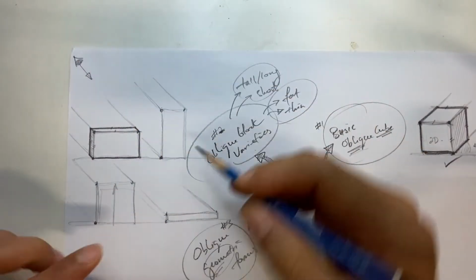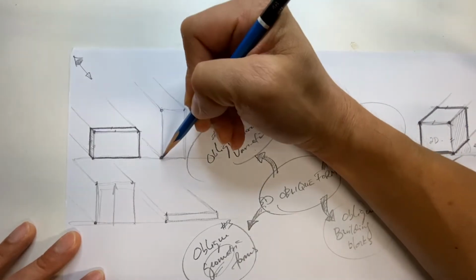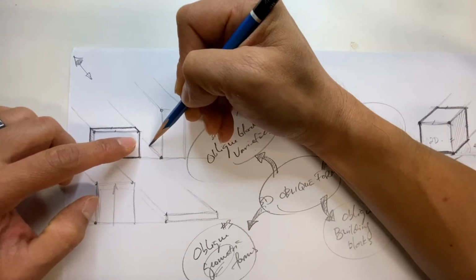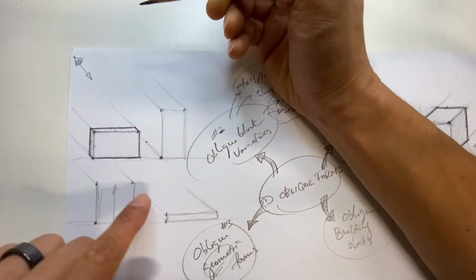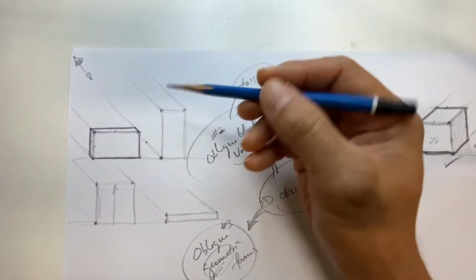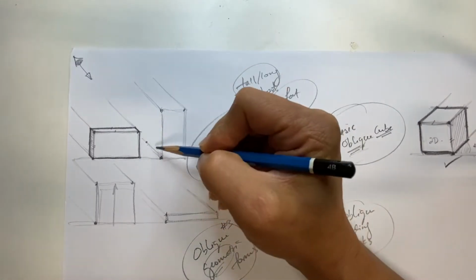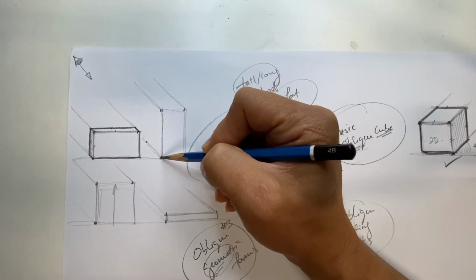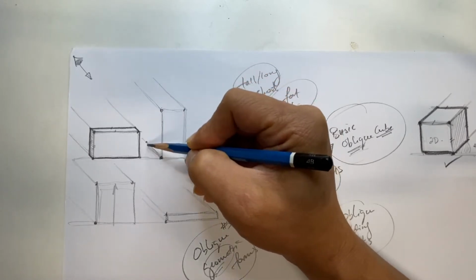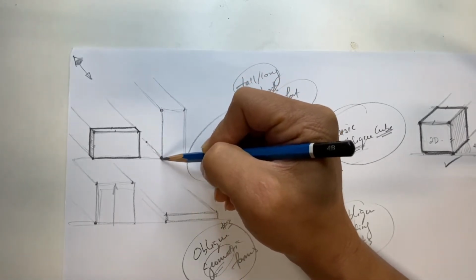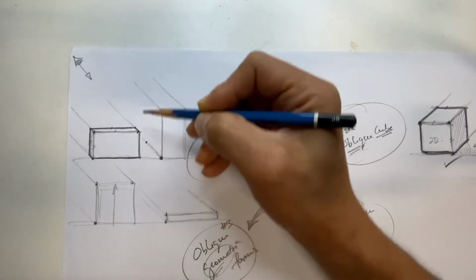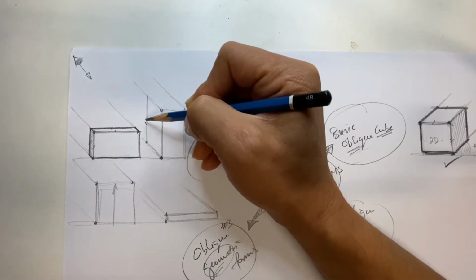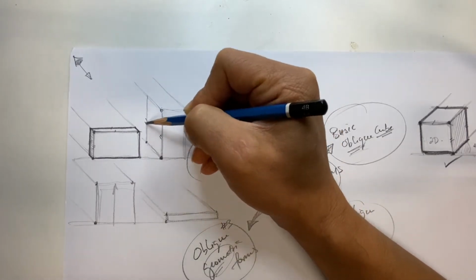Now for this one, I'm going to make it slightly fatter. I'm going to project the lines to the left at 45 degrees, and I'm going to stop here, slightly fatter than the first one. So how do I manage the back? Look, you simply bring the lines for a walk. Look, this one is a vertical line, and this vertical line at the back will start here at the bottom, just like how you started here. From the bottom up, vertical line, parallel. See? Parallel. Once you reach the top,